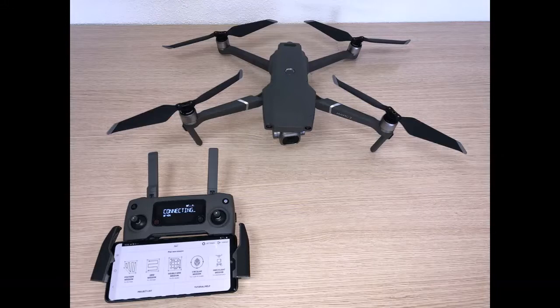A practical example of aerial photogrammetry with a drone combined with terrestrial photogrammetry. In this example, data capture will be carried out using a drone equipped with a camera, followed by a series of flight missions with the help of the free mobile application Pix4D Capture. The equipment for this mission will consist of the drone, its controller, and the compatible smartphone or tablet connected to the controller. The processing of the photographic data will be carried out with the RealityCapture software.